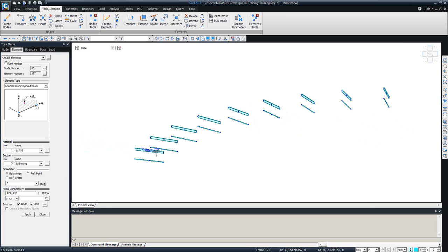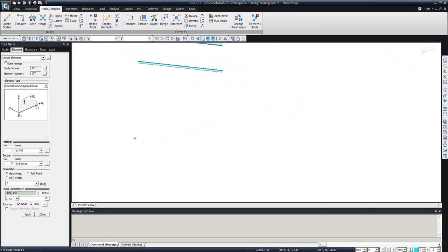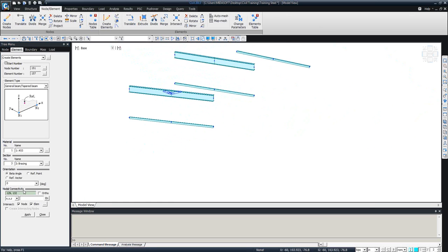And now to create those cross frames, what I can do is simply select here, and then you see the software automatically recognizes the center point. Why? Because we have a filter in the very right bottom corner right here. You see that it mentioned 2. So it means the software automatically considers the center point of each element.